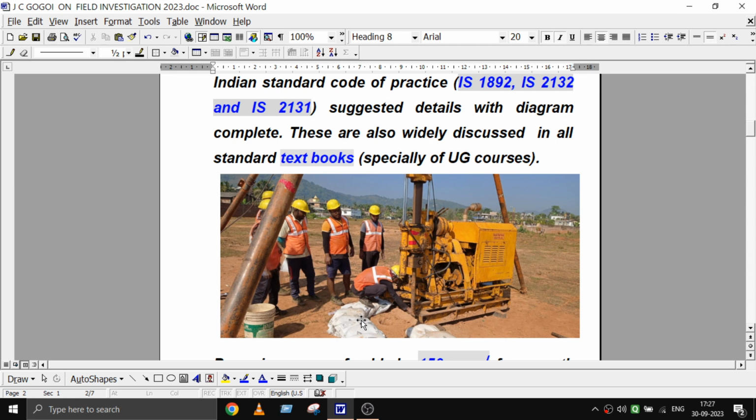For a 10-meter bore, if you are drilling using percussion drilling, the soil to a distance of half the depth is disturbed, because this operation is constant hammering using 20 bar pressure. That means we are compacting.